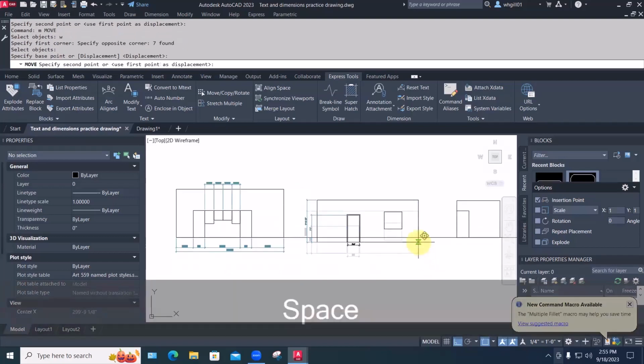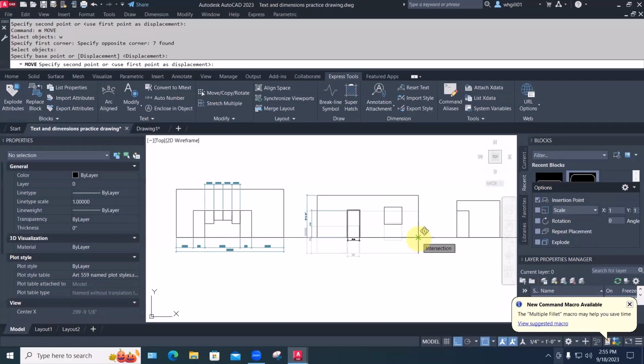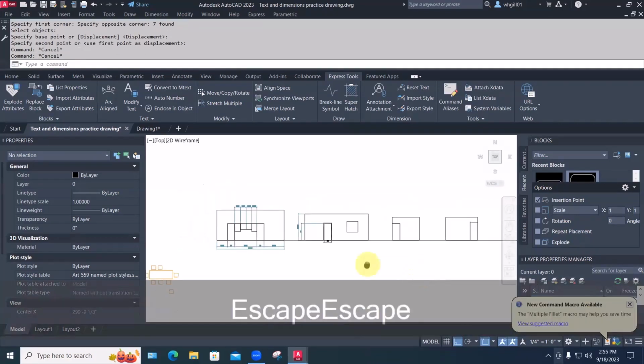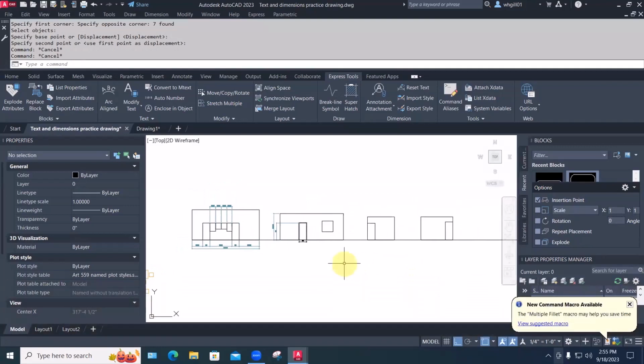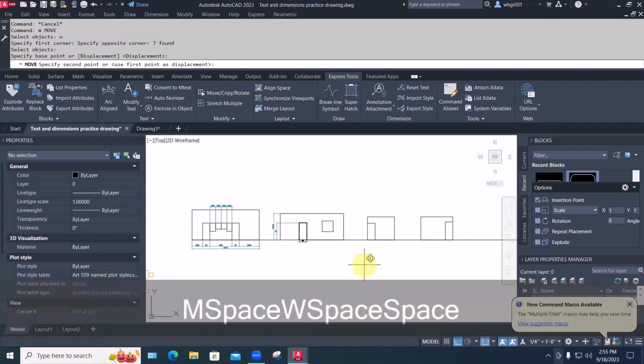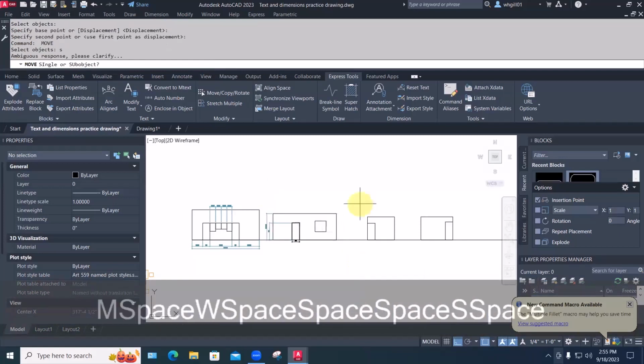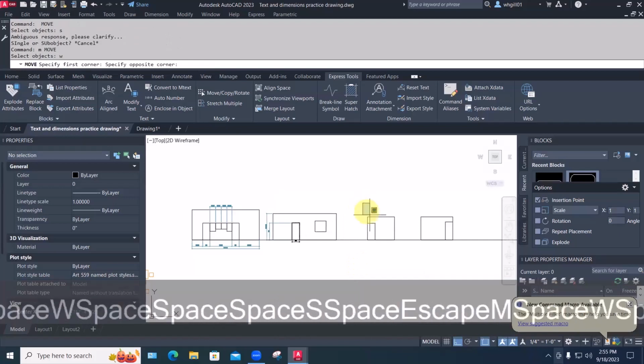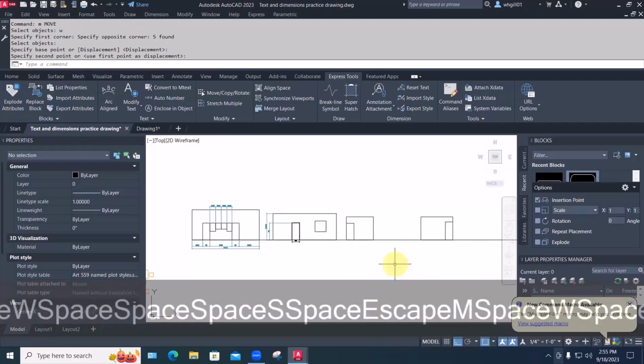And here I can go from here either up to perpendicular or to intersection, or any one of the snaps that's going to pick that line. And then I don't want to take up more space on the sheet than I have to. So I might just move these in here, leaving room for dimensions and things.